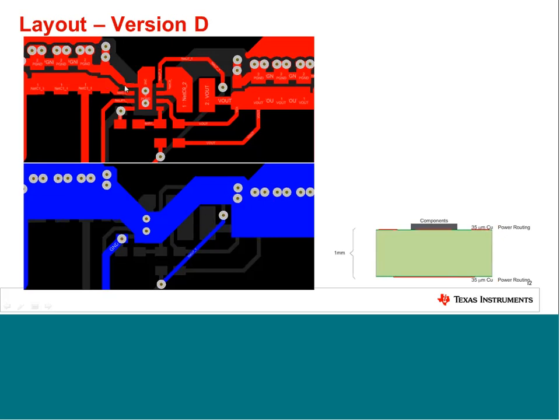This way, the layout itself forms a capacitor with 2 plates, one on top and one on bottom, and a certain capacitance related to it. The board is still the same here, 1 millimeter thick and 2 layers.